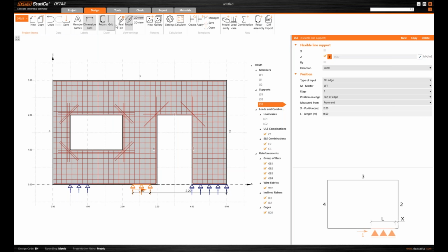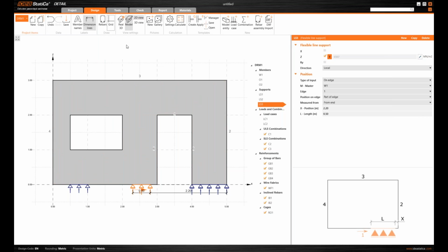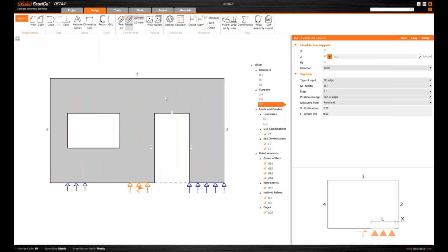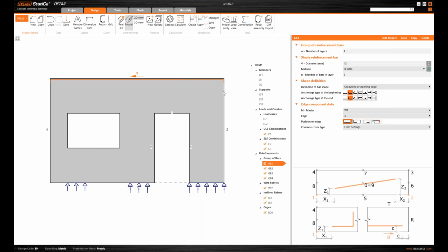Let's say I turn off the reinforcement, then click on a reinforcement rebar, and that rebar is displayed in the 3D scene, but only one rebar. This is a great improvement: if you have a diaphragm with many reinforcement rebars, you can very easily turn them on and off, and it's more transparent for modeling and putting the reinforcement inside the detail.